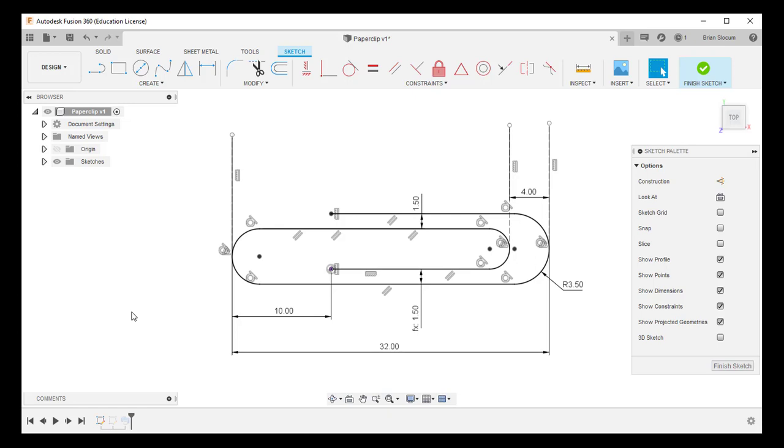So if I go here and I edit my sketch, just to show the dimensions, we start at our origin point, and this is going to be really critical here because that origin point needs to be common for both the profile, i.e. the circle, and the path, i.e. this sketch.